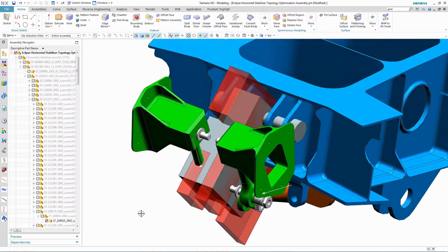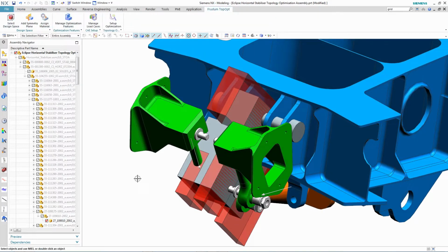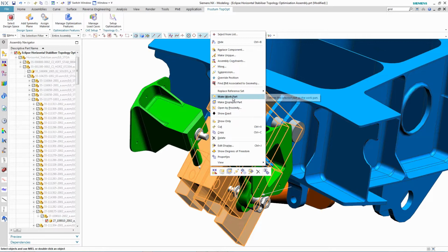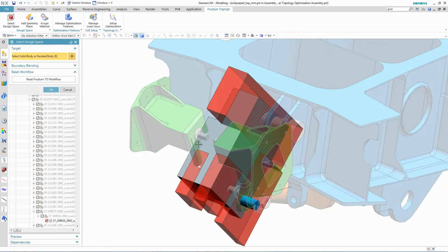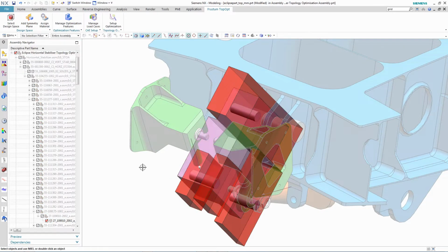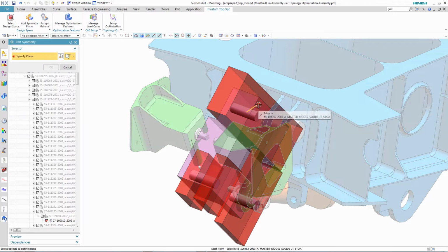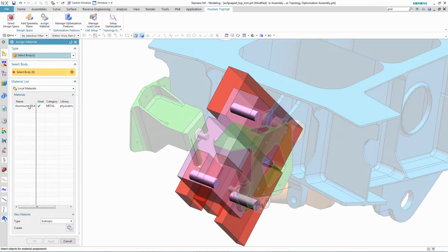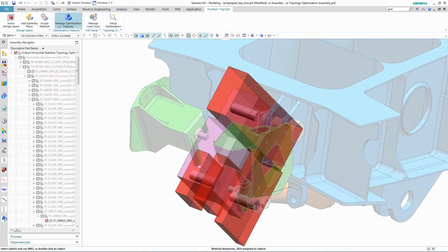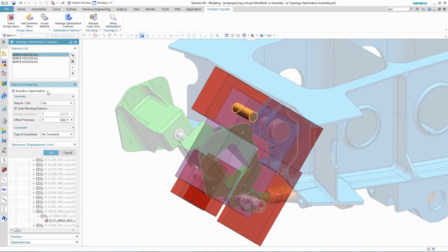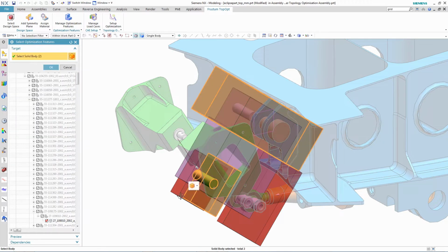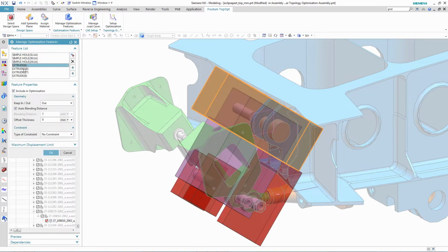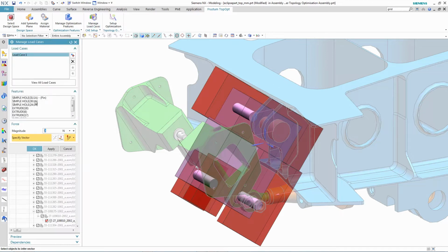the design. The designer picks the topology optimization solution from the NX interface and follows the simple commands in the menu that are laid out in the steps of the process. The designer first identifies the design space, symmetry plane, and material for the design space. The designer also notes that there are pin connections within the design space, which the optimizer will then maintain as it determines the part shape. The designer also identifies the red areas as the keep-out zones.